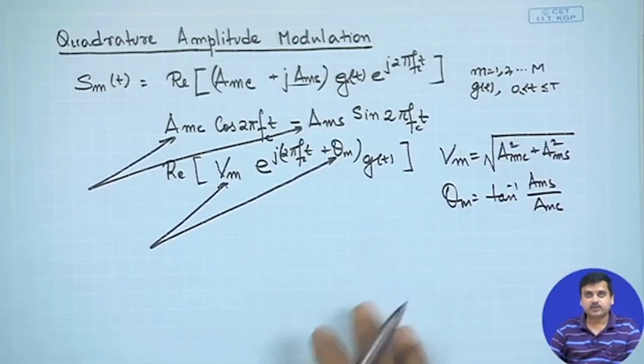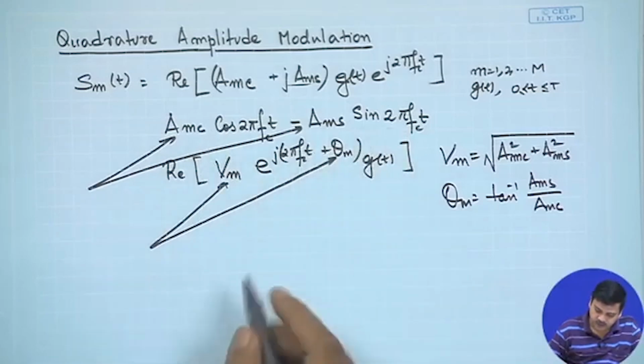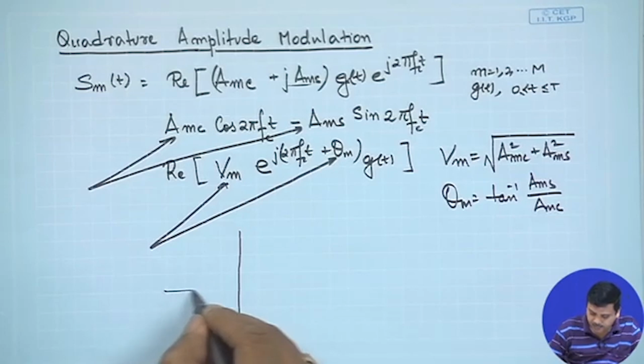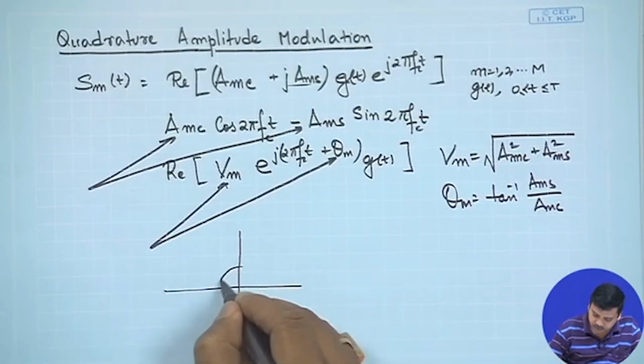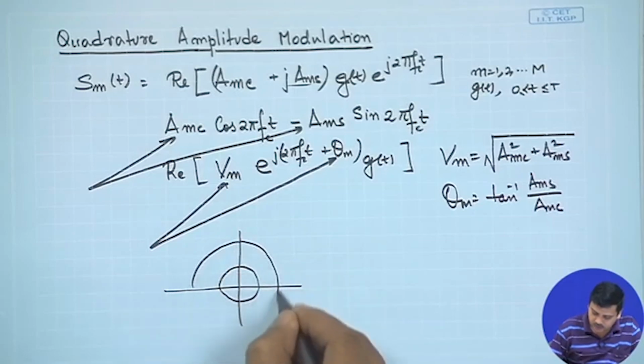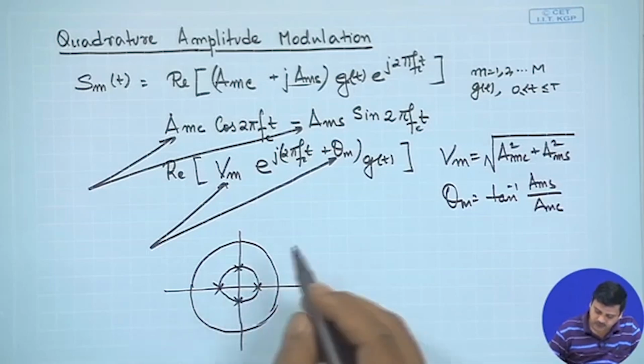These are some of the things we have discussed, and then we asked what the corresponding signal space diagram, or constellation diagram, would be. If we combine the amplitude and phase modulations, then one could use M1 level amplitudes. As an example, we took 2 amplitude levels, and then one could use 4 phases.